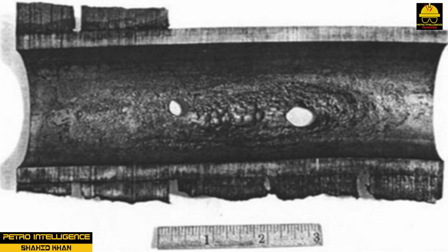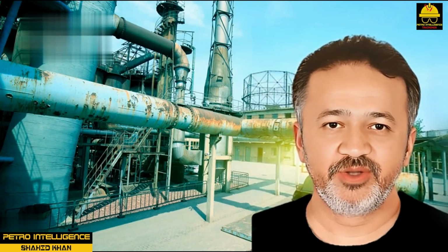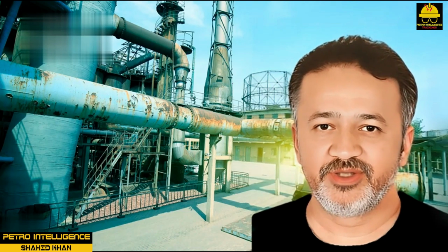Corrosion fatigue occurs when thermal warp, caused by rapid heating or cooling, affects a weakened area, or it may be caused by cracks created internally from the action of applied cyclic stresses. Caustic cracking is characterized by metal stress, embrittlement, caustic water, presence of silica, and a small leak that focuses stress on a small area. Corrosion prevention is characterized by maintaining pH levels in boiler feed water, removing dissolved oxygen from water, using chemical treatments, and following established out-of-service and blowdown procedures.